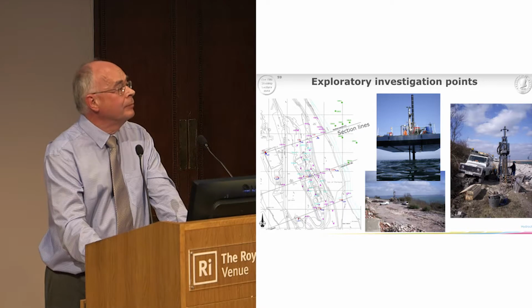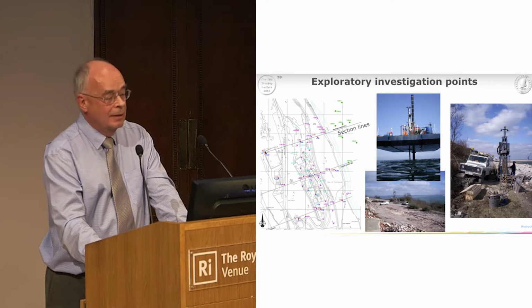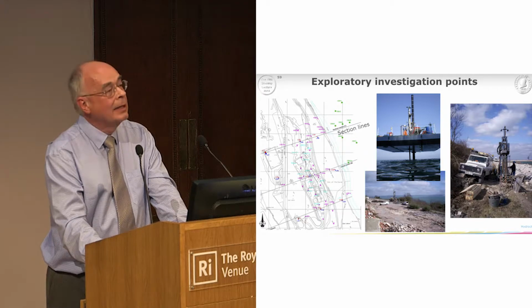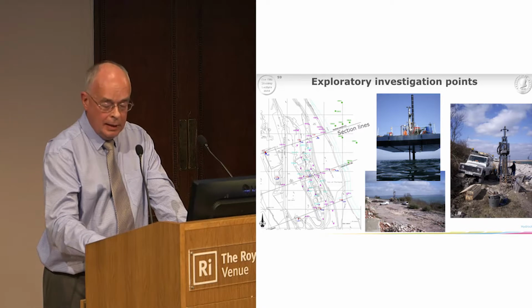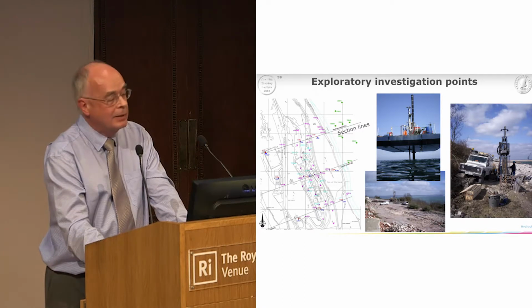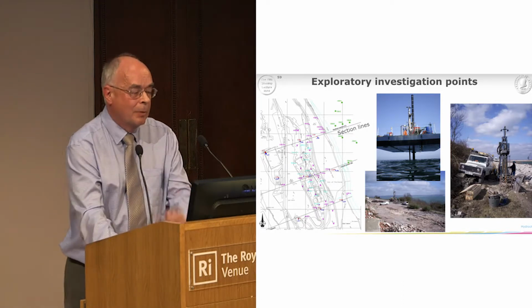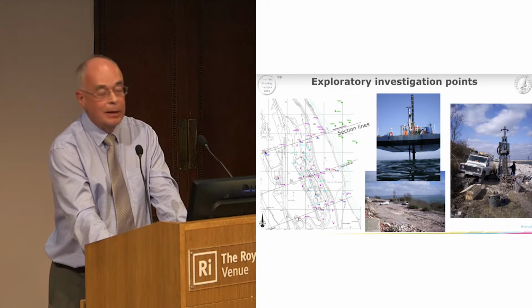We did a site investigation next, about 8 boreholes in the sea, 53 boreholes on land, up to about 100 metres deep. These were designed to give us 3 large, high-quality section lines to work on for stability analysis. There were also some boreholes in between, some general infill geotechnical design boreholes.